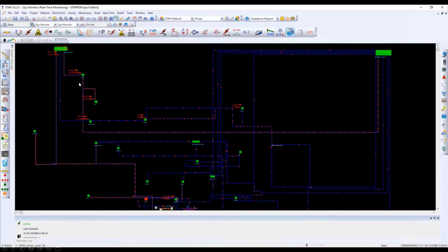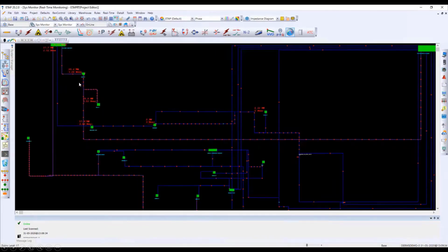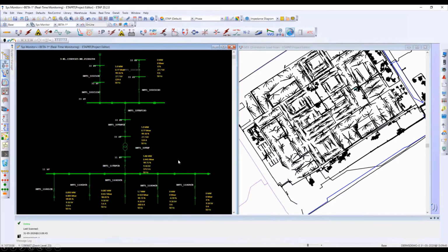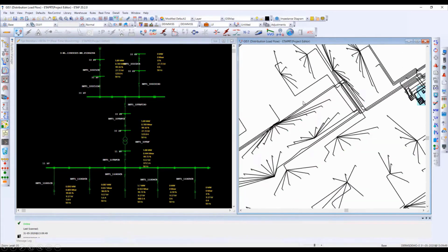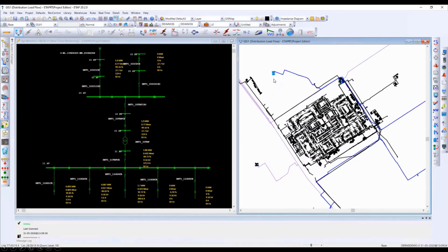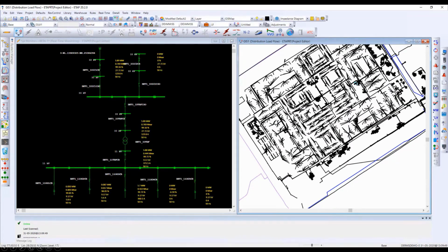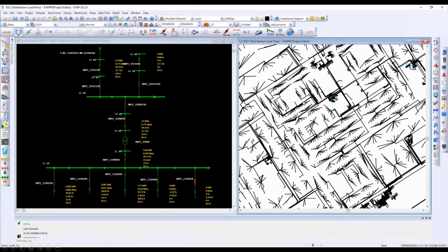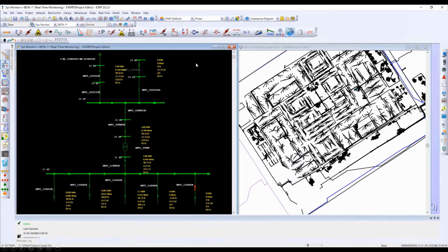The ETAP digital twin model offers different views to visualize the system connectivity. The feeder distribution view provides visualization of power flows between different areas of the network. Next, the visualization views include substation views, which provide a one-line view of the power distribution, and a geospatial view, which allows you to visualize the digital twin as it is geographically arranged. Note that geospatial views cover the entire model distribution network. The iDLS controller uses switching devices modeled in the digital twin to evaluate how much generation and load is available in the existing model, eliminating the requirement of a complex system and leveraging the existing digital twin already used for simulation.